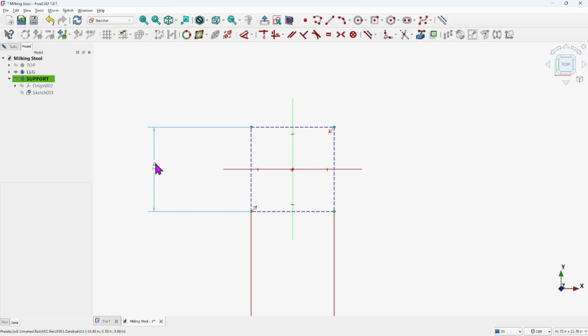Now, my plan when I started off this video was to build a quarter of it and then use the mirror command, because I am trying to use commands in the Part workbench, which is recommended by FreeCAD, to minimize what you would do in the Sketcher workbench. So that's just my mindset. I'm just trying to get there and try to help you get there too. But for some reason when I did the mirror, because the faces or the sides weren't intersecting, it didn't recognize it as the same body. So that's something I need to work on, and hopefully I can figure it out.